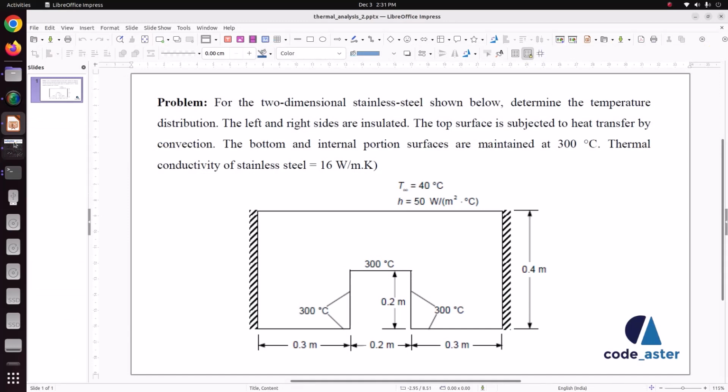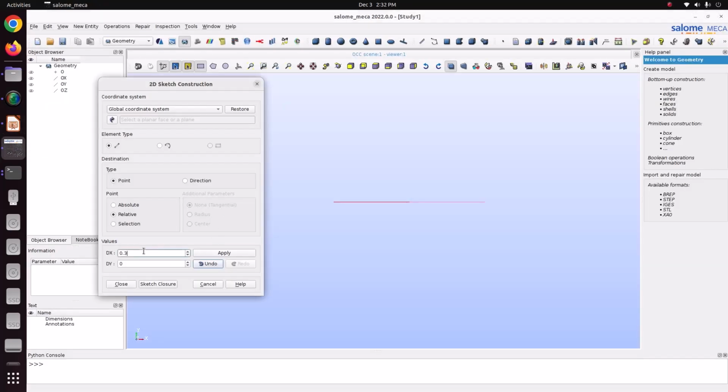In relative, only the direction and the increment matter. Now we are in this position, we need to specify the value. If you are using absolute, we need to specify from the 0 position. So we are in relative, so just keep it in relative. Now x is 0, y is 0.2. You can see it here.